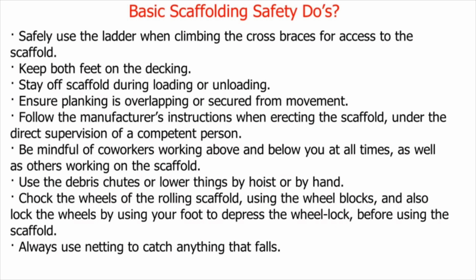Use the debris chutes or lower things by hoist or by hand. Chock the wheels of the rolling scaffold, using the wheel blocks, and also lock the wheels by using your foot to depress the wheel lock, before using the scaffold. Always use netting to catch anything that falls.